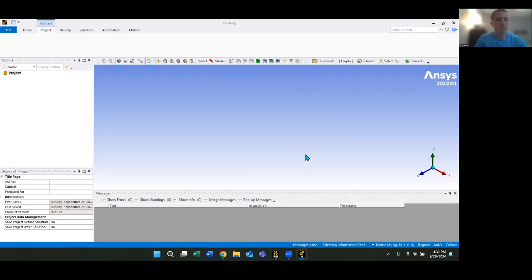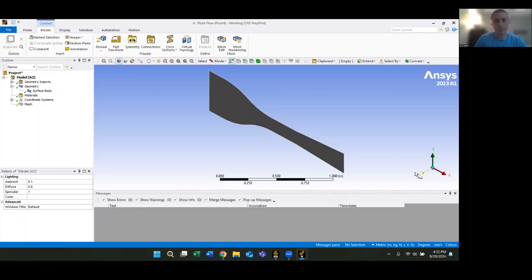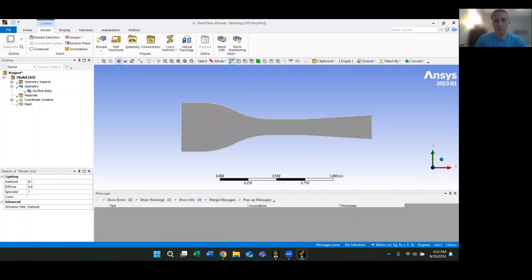All right, the mesh is coming up. I'd like to make it normal to the Z because this is in the XY plane. One thing to note is to make sure it is a surface body. This will actually be a whole body. If you did everything right by making it plane, then you'll have that.